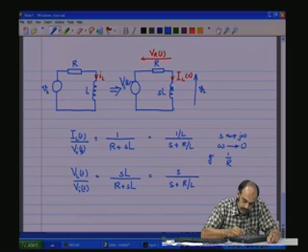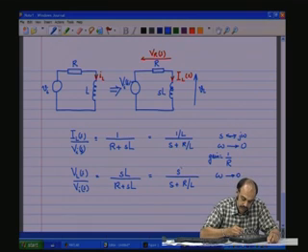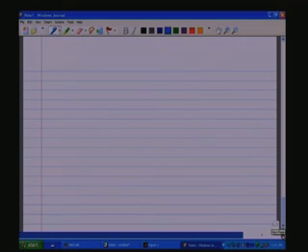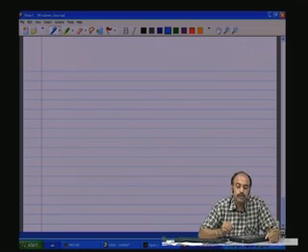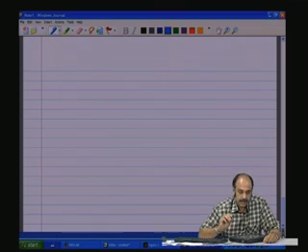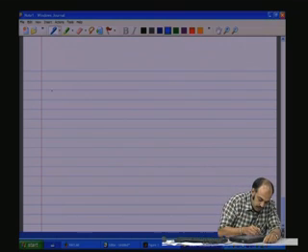So, this is the gain, and in this case, as omega starts tending towards 0, this will also tend towards 0, and then you will see that the gain tends towards 0. Gain tends towards 0. So, that is basically the idea that you will have to get from this pole zero analysis, the transfer function analysis. Let us do one more circuit, which is the RLC circuit, which combines both together.